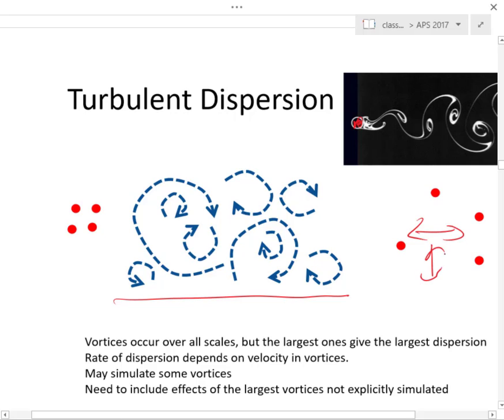And so the way we might think about this is that the dispersion process in porous media is going to depend on how fast the velocity through the pores is, but it also is going to depend on how big the grains are, right? Because if it's splitting, going around the grains, that'll be an important scale. If the grains are bigger, then it has to go around those bigger grains, and it'll spread further.